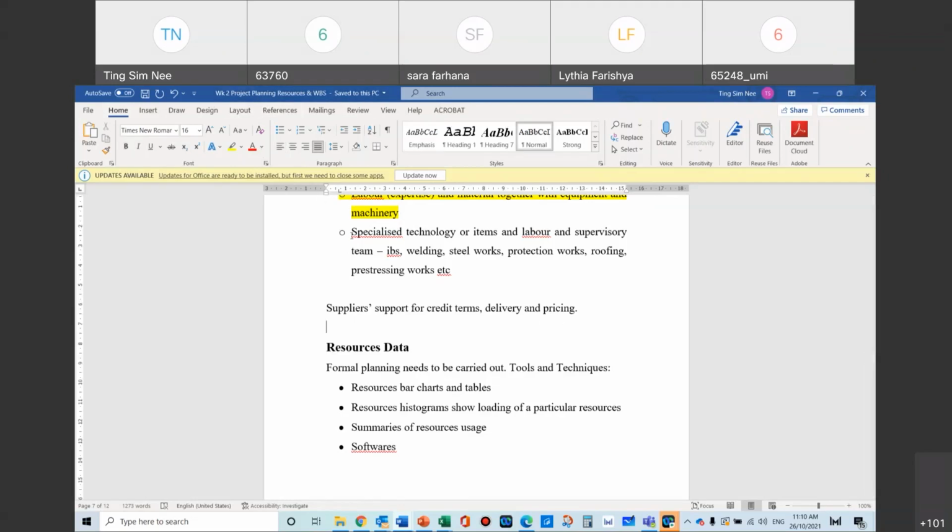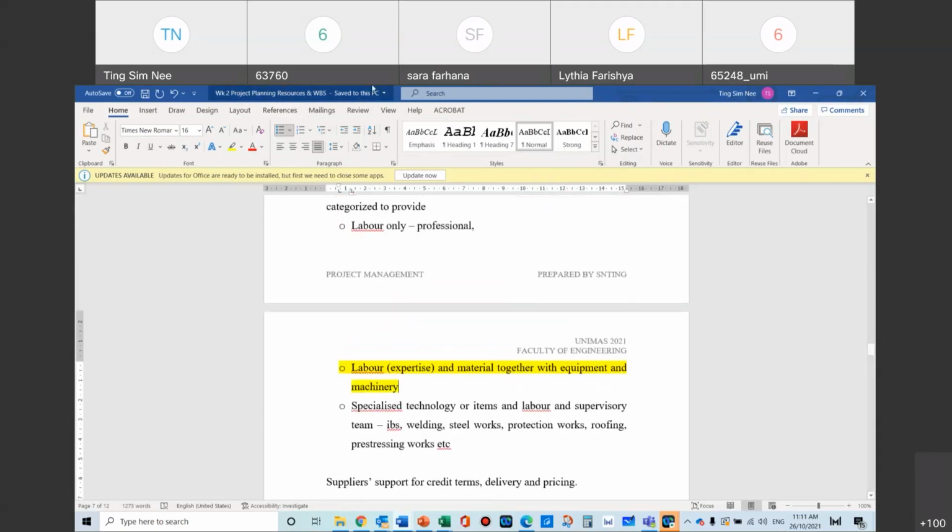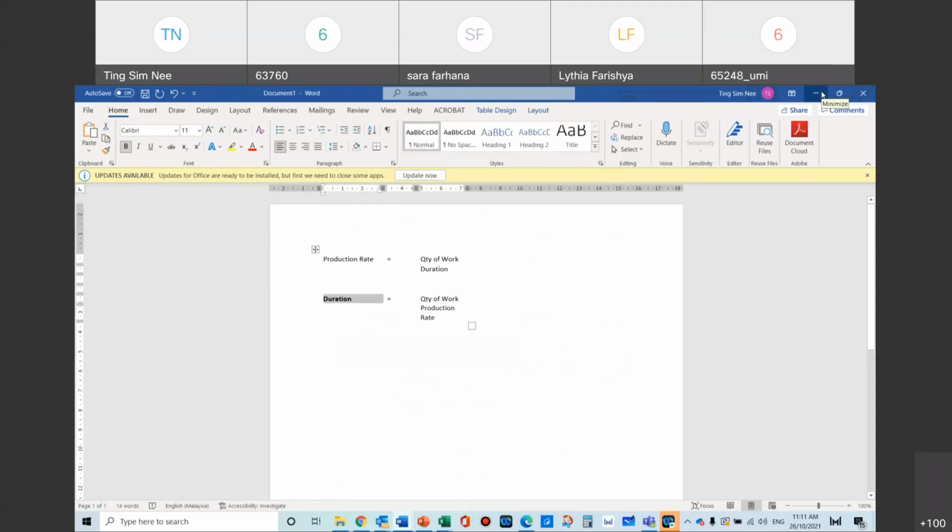Okay. So what I really want you to go off with today is basically the appreciation of doing these resources work breakdown. That's the first thing. And the second part is associating the resources, doing the overall resources data sheet first. From there, we will start to use these resources data sheets in many different ways, which I've mentioned. Material, labor, machineries all have their own purpose on these resources, because it will actually affect our next step, our time and our scheduling.